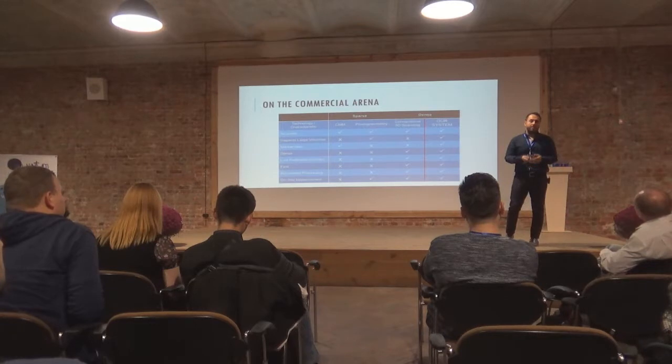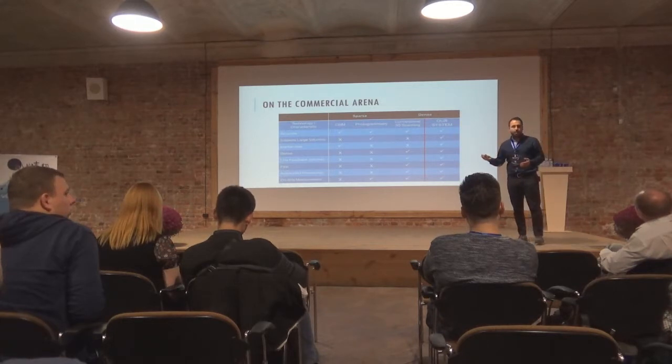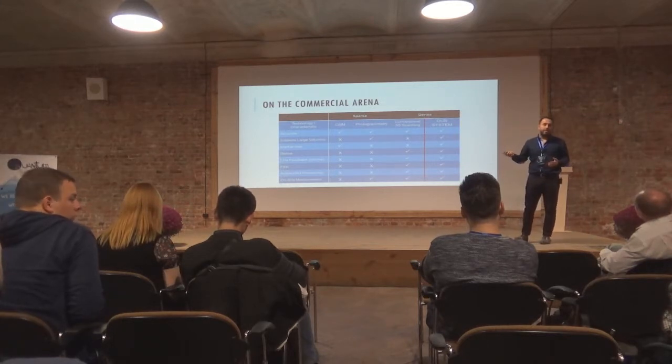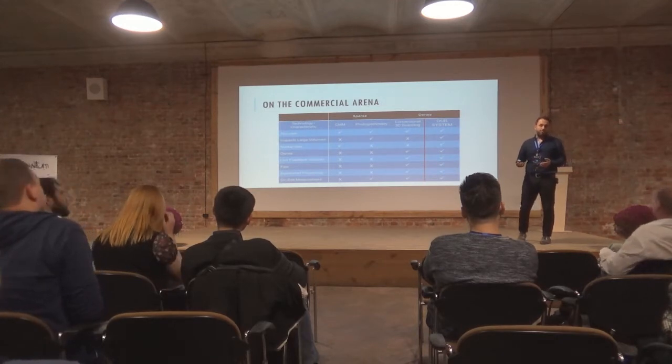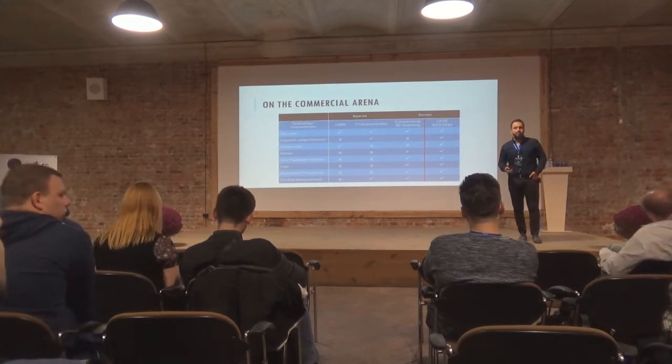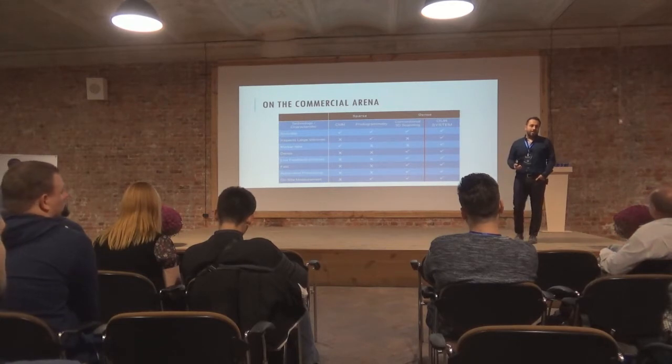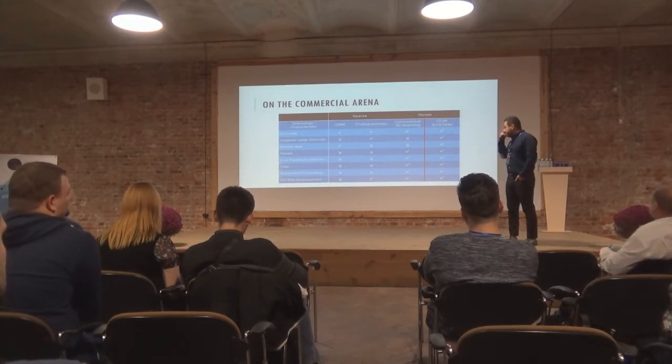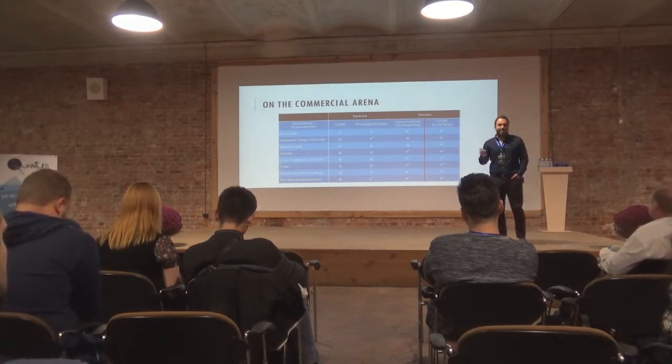Whereas in software, you can even compensate for the heat of the camera. You can calibrate, you can have a model of how the camera heats and what happens when it heats up, and just add it on top of your bias correction. So in that sense, it should be replaced at some point.